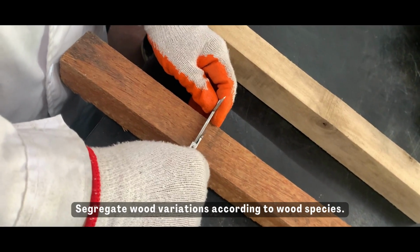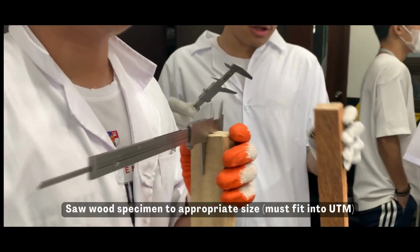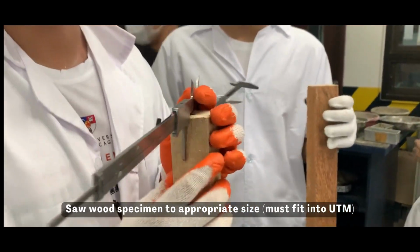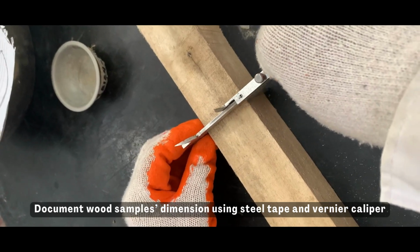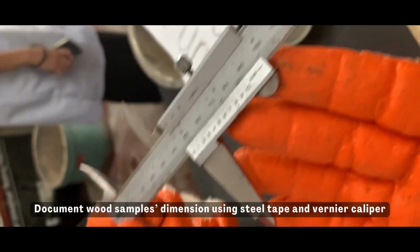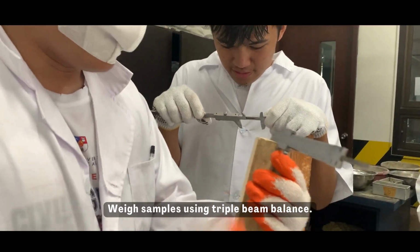Segregate wood variations according to wood species. Saw wood specimen to appropriate size. This must fit into the universal testing machine. Document wood samples' dimensions using steel tape and vernier caliper. And lastly, weigh samples using a triple beam balance.